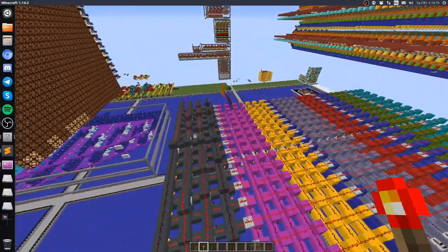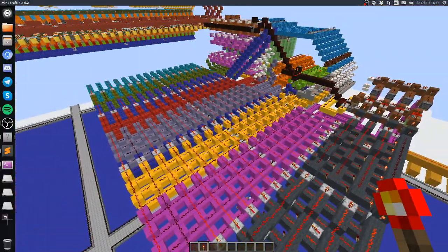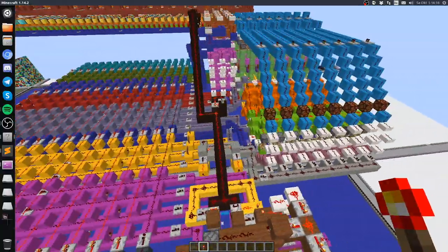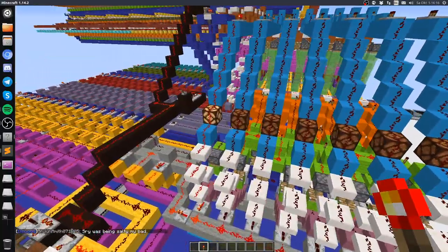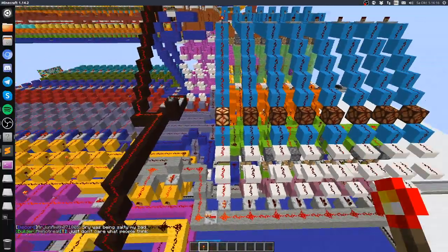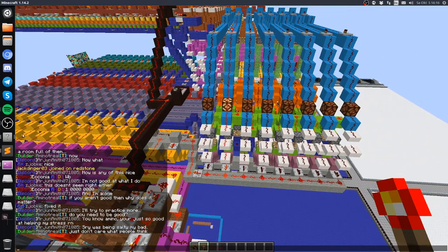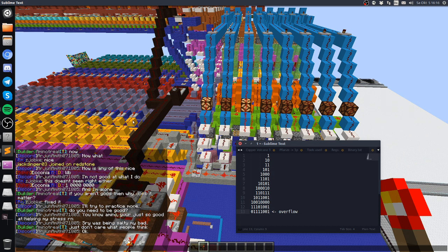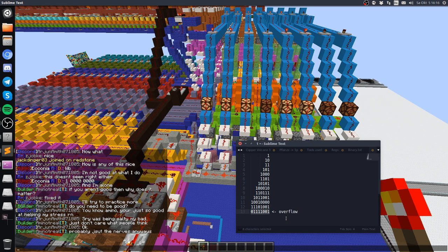So this jumped back here. This gives it a bit of time where you won't have any value on the display, and then we go to the first one, which is also 0, and the next one has that 1 there. This should loop until we get some form of overflow. It will do the same stuff as before, line 4, line 3, line 4, line 3, and so on. It will always jump back, and when this one has an overflow, it's gonna jump to the end of the ROM and spend some time, and then start all over again.